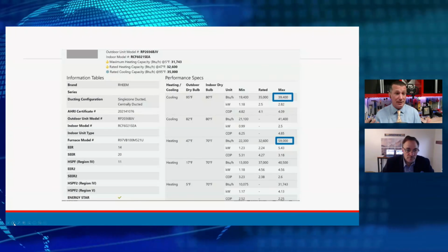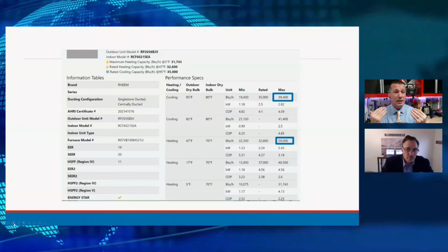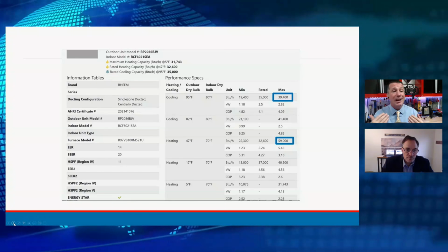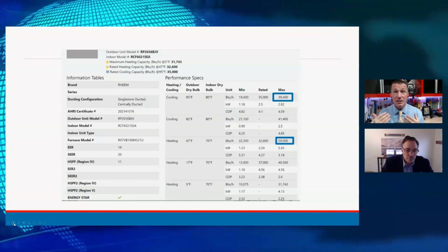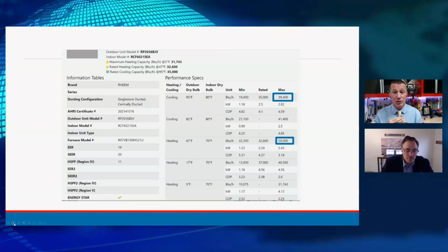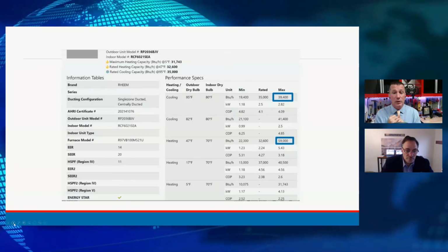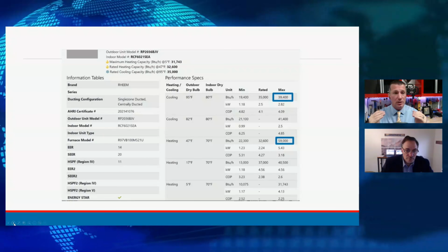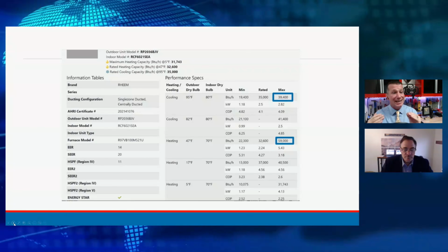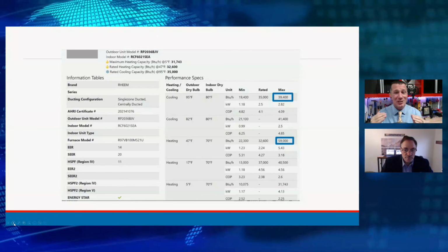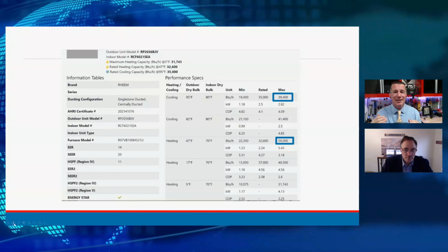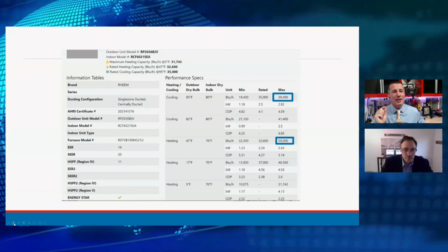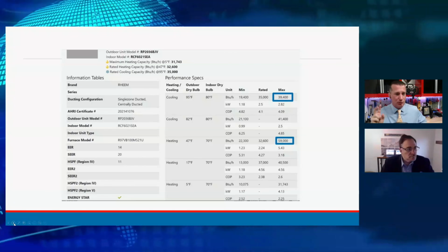In a lot of our new technology, we are measuring the pressure on our motor and calculating that into static pressure, like with communicating thermostats, so we're actually calculating how much static pressure is on our ductwork so that we can limit the amount of airflow in our system and not get too much static on our ductwork. Remember, that's the whole reason we redid our SEER ratings, was because of our poor ductwork here in the United States. So I limit my capacity on my outdoor unit so that I'm only producing a 3-ton unit for cooling.